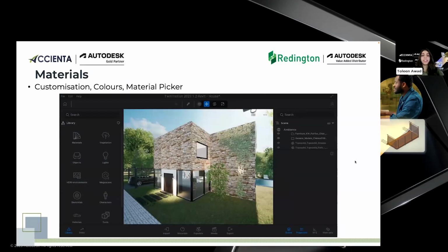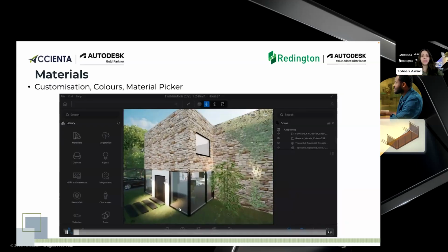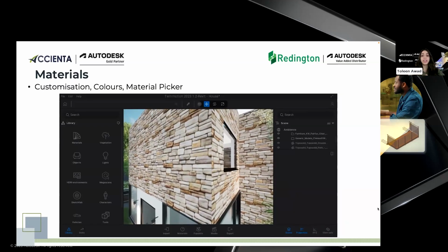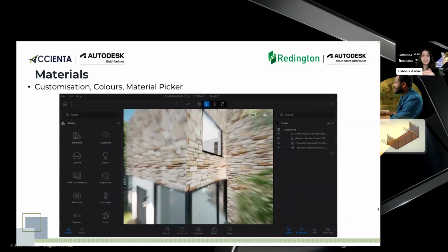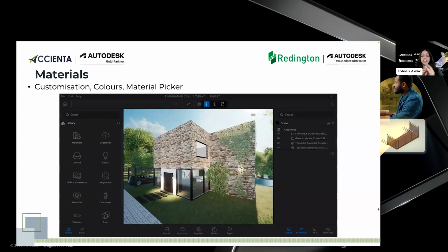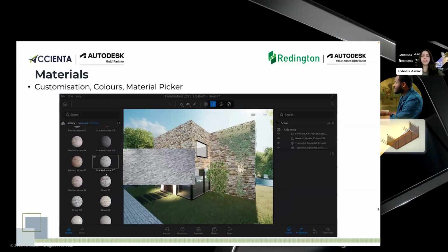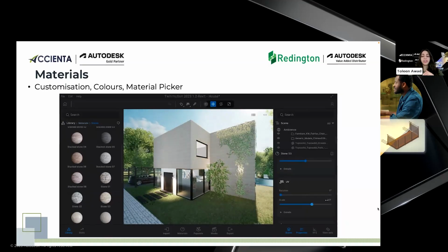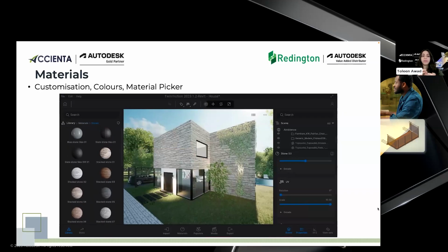Next please. Great. Once we saw how we can add elements, now we can see how we can add materials. I'm zooming in to show you how the material looks once we extracted it from Revit itself. We don't have any textures or bumps. If I want to change that, I go to the library and then to materials. You can scroll down. We have wood, brick, plastic, and fabric as well. There are a lot of surfaces and materials you can use. I'm just going to stick with stones. When you hover over a material, you can see how it looks. You can change the scale of the material, just drag and drop it, and choose whatever material is applicable to your project.